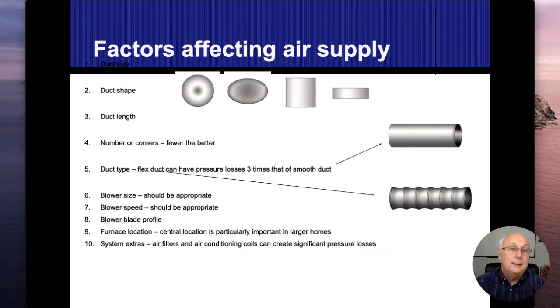So our shortcut method is to take the thermal imager around and we shine it on all the openings where the exhausts are coming out, once the furnace has been running for about 5-10 minutes already. I would not only want to see that the grill itself is warm, but if it's close to the wall, I actually like to see flame patterns on the wall so that I know heat is hitting that and it's coming out of there. All right. Same thing for the ceilings and so forth. If I see just warm air, I typically go over the area and I just use my sock. I take my shoes off in most homes. Otherwise, I use the back of my hand.